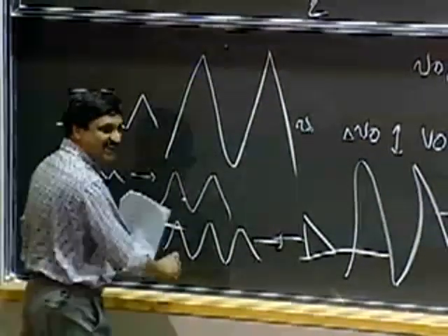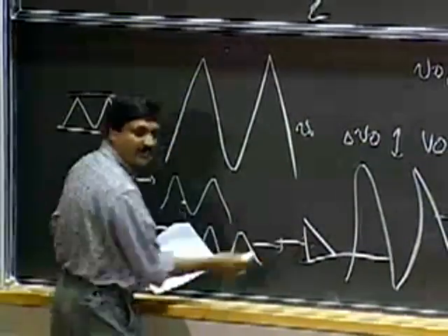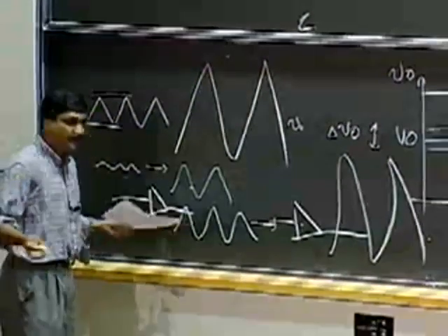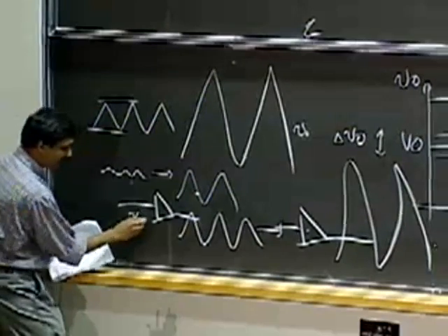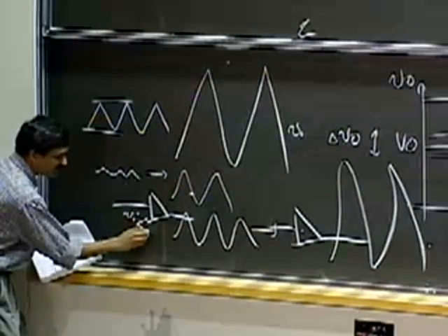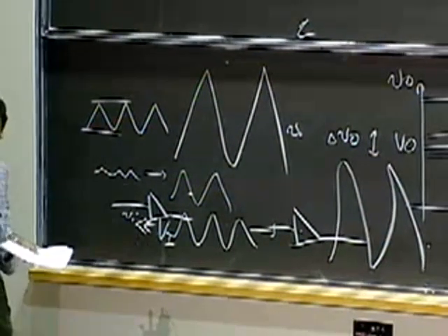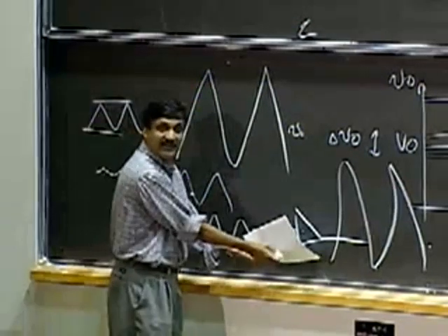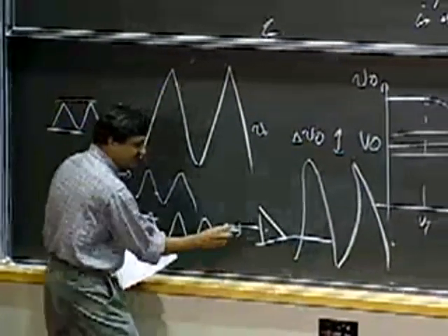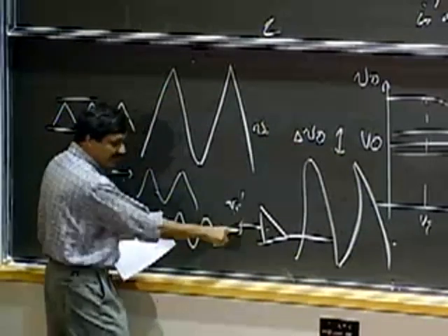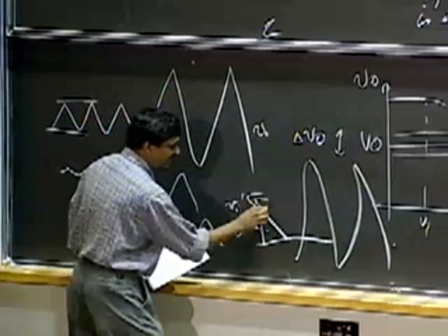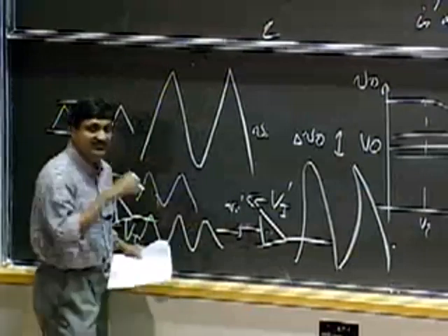All right. So how do you make this work? What you have to do is this VI has to be much smaller than the bias point VI on this one. I have to build a different amplifier, choose a different set of parameters such that VI prime, which is the VI for this guy, is much less than capital VI prime for this guy.